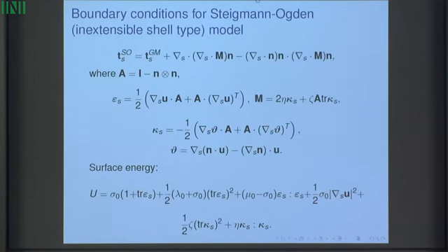Now, the Steigmann and Ogden model is an improvement in some ways on the Gurtin-Murdoch model. So we still have this Gurtin-Murdoch component over here. Everything which was on the previous slide goes here. And then you have these 2 additional components which are higher order components. In the Gurtin-Murdoch model, you typically have 2 derivatives of displacements, so your stress interactions on a boundary depend on 2 derivatives of displacements. In the Steigmann-Ogden model, you actually get 4th derivative of your displacement. So it's a high order model because of that.